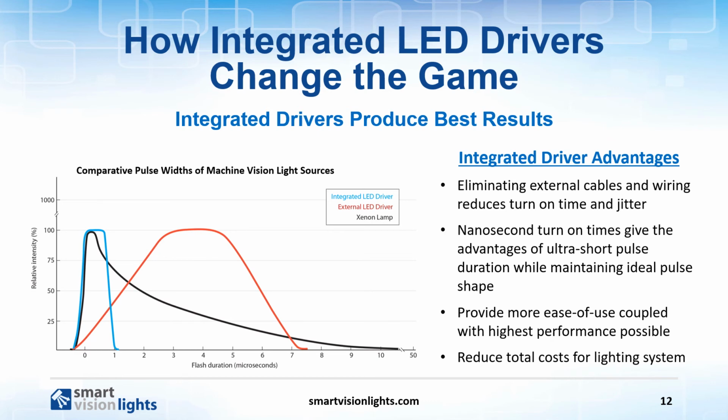Smart Vision Lights took such an approach with the development of its NanoDrive driver to minimize resistance and parasitic electrical losses from external cables. LED lights featuring this technology are thus capable of quickly delivering tens of amps directly to the LED die to achieve full power in 500 nanoseconds or less with comparable shutoff time.